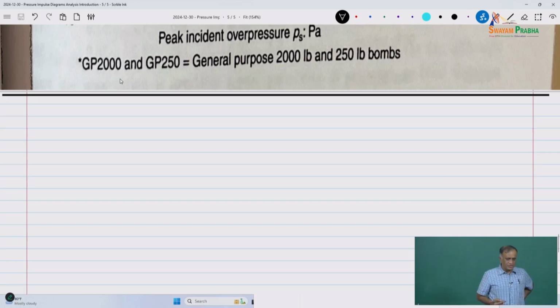So for example, the SDOF, a whole Excel program of an SDOF response. You give a structure, maybe you can develop it for steel, concrete, masonry, precast, pre-stressed, anything that you want. Your inputs are going to be the structure properties, the sizes, usually if it's a wall, 1 meter width or 1 unit width is considered, and then develop all the section properties as we will discuss in the next couple of classes, and then develop the response of it.